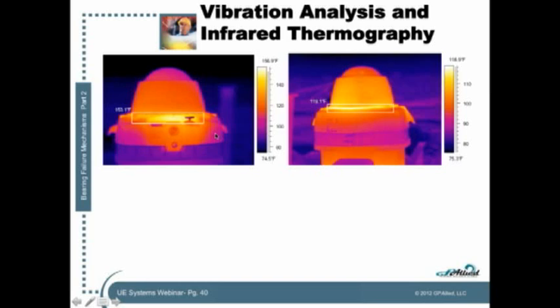These motors were roughly the same size, definitely the same load as a percentage, definitely in the same environment, and should have been very, very close to the same temperature. So from a thermography perspective, we were able to determine that one of these motors has a bearing defect.